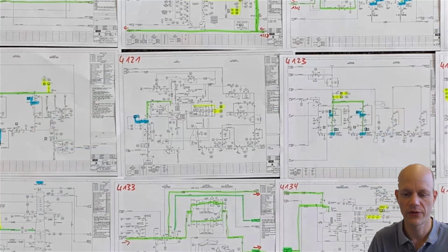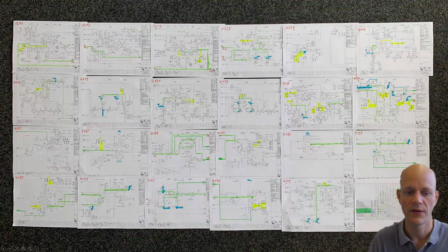And you see here the process we did. So we actually worked with printouts and PDF files of the P&I diagrams to derive the rules. This is a one-time activity, and once you have the rules, you can apply them also to different plants. Here we see the photo of 24 different P&I diagrams, which we analyzed for one of the plants, where we also try to recognize the different dependencies in a plant between different elements to come up with the rules.